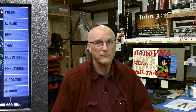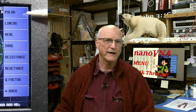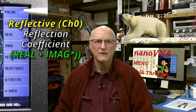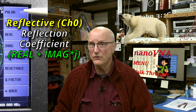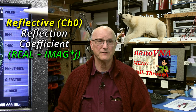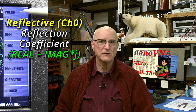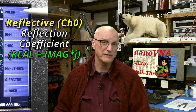Next, we have to go to the More menu item for the rest. We tap on the More menu item of the Format menu. At the top of the list is the Polar item. What does this mean? In reflective mode, this is where we get a real view of the reflection coefficient. The horizontal axis is the real portion of the reflection coefficient, and the vertical axis is the imaginary portion.